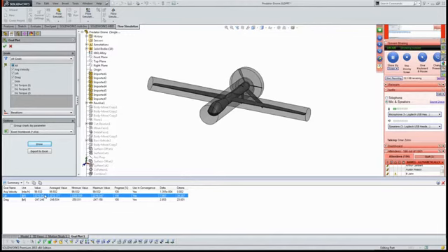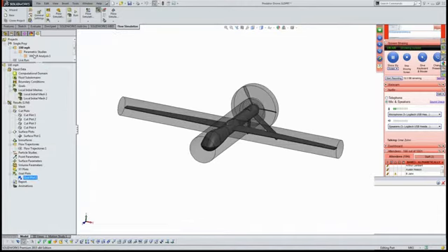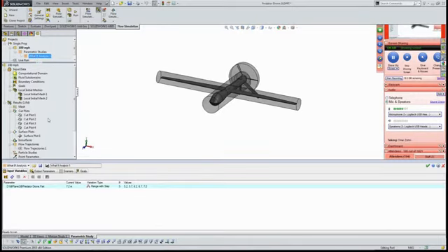Let's say that I know this drone weighs 1,500 pounds. I can see here that with this length of wing, I'm getting a lift force of 2,200 pounds. So I could potentially argue that this thing is over-designed. So one of the really powerful things that you can do with a simulation tool that's embedded inside of your CAD package is I can run a what-if analysis.